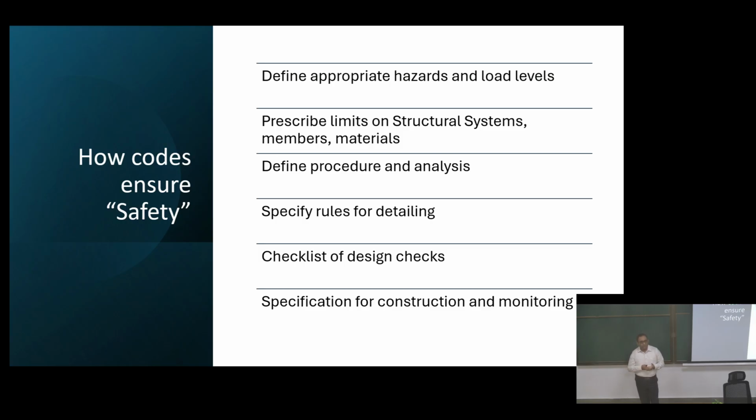Do you know what a response spectra is? And are those response spectra different for different return periods for earthquakes? Yes? So those are different hazard levels. If it has a higher return period, that means it's a much more massive earthquake than a lower return period. So for a higher return period earthquake, you probably need to consider higher forces.